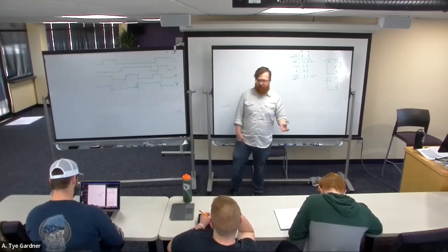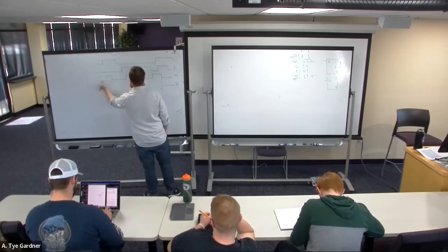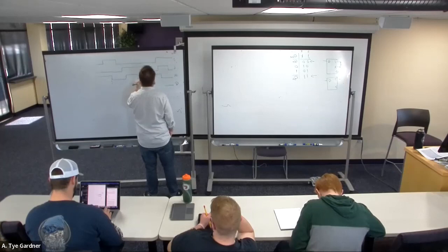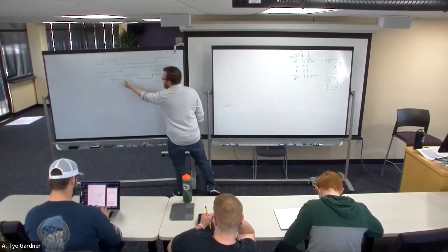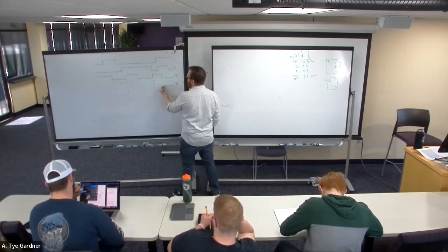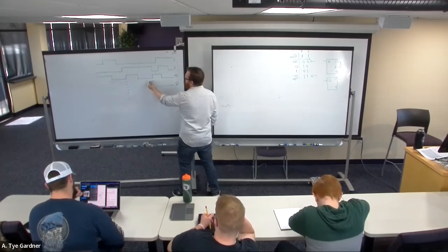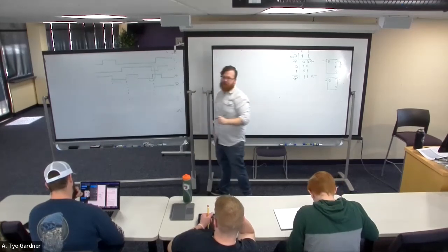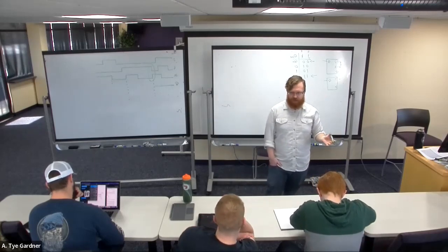If this were a falling edge device, instead of caring about the rising edge, I start caring about what the falling edges are doing. And let's say I do the same thing and I assume it starts at 0, it reaches its first falling edge, and see how those change at the same time? I don't meet setup and hold times.